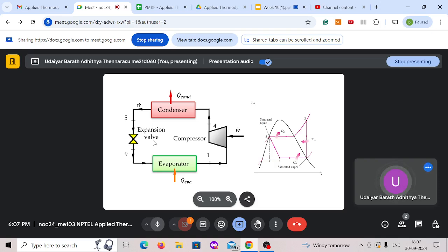when your inlet temperature is less than the inversion temperature, there will always be a temperature drop with pressure. But if you lie outside the inversion temperature, you will have an increase in temperature.